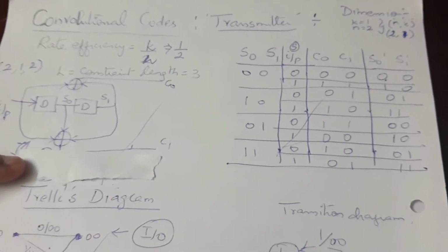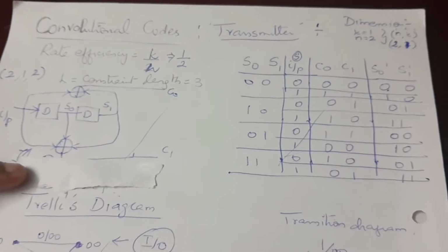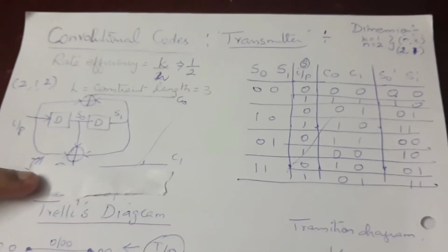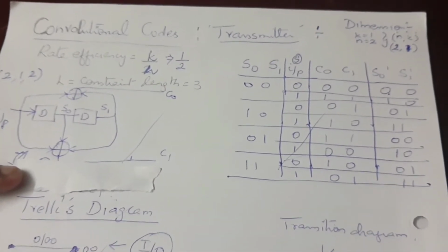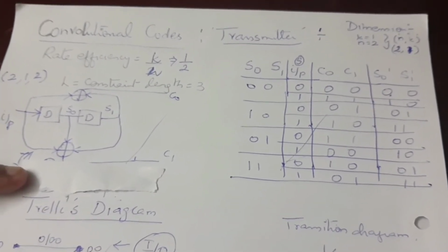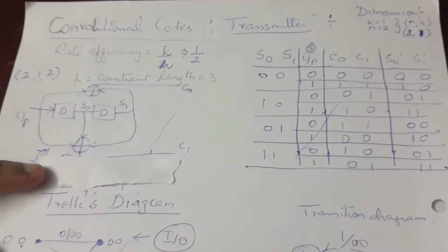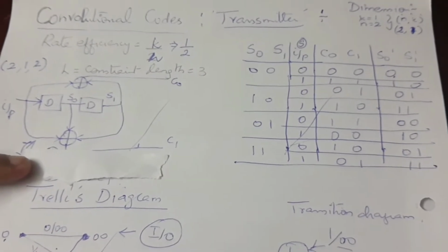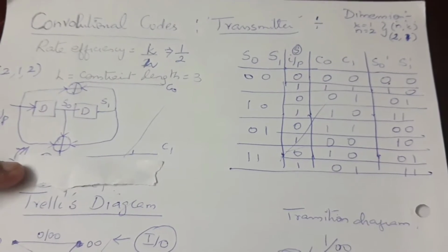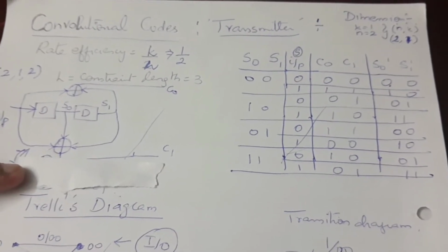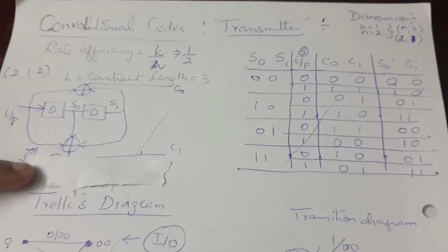Convolution codes are going to produce output for a single input generation. The convolution codes can be worked on the encoder side as well as on the decoder side. This convolution code uses the best decoding algorithm, which uses the maximum likelihood algorithm, which we call the Viterbi algorithm, in the receiver segment. Hence, convolution codes are playing a vital role in almost all modern wireless communication systems.